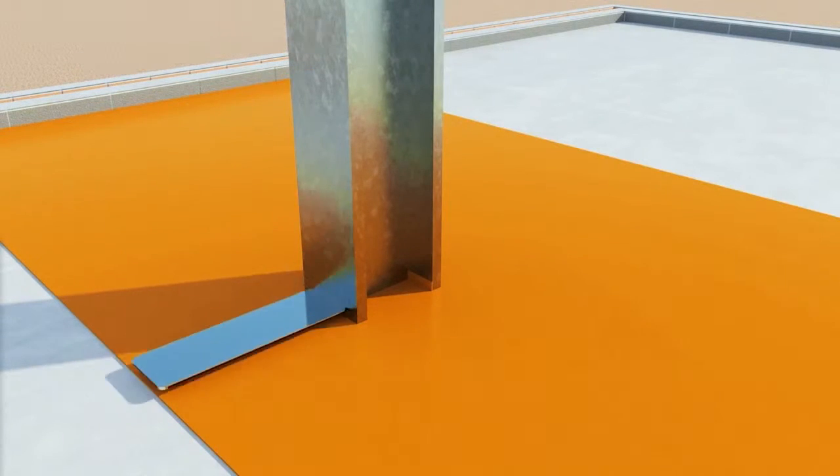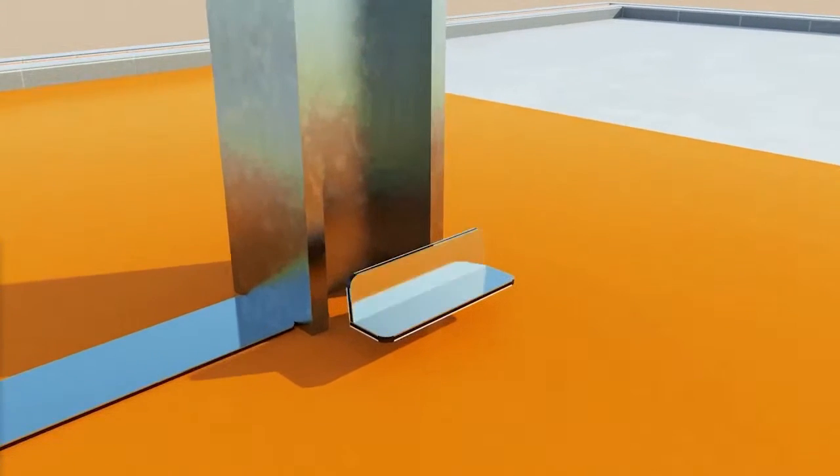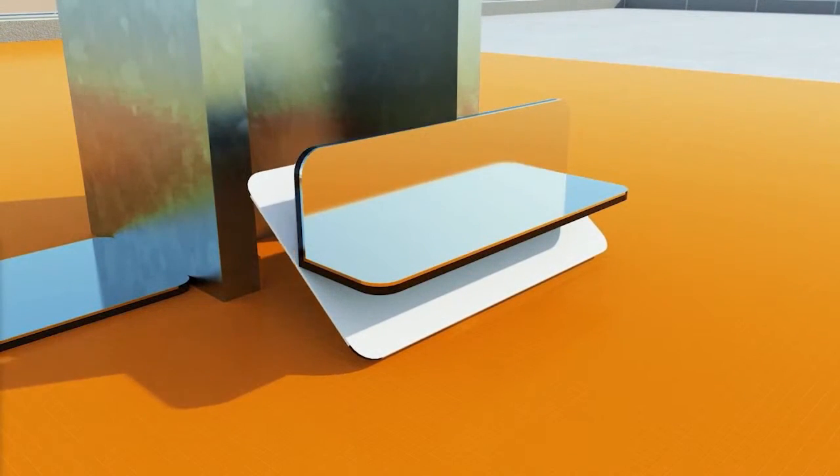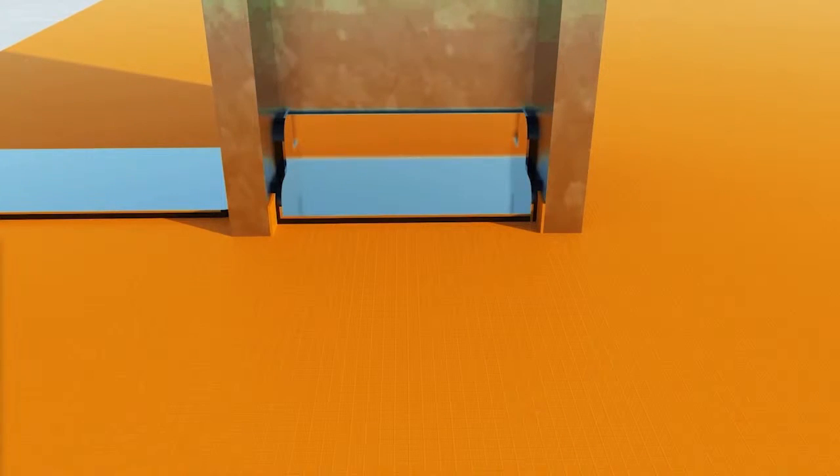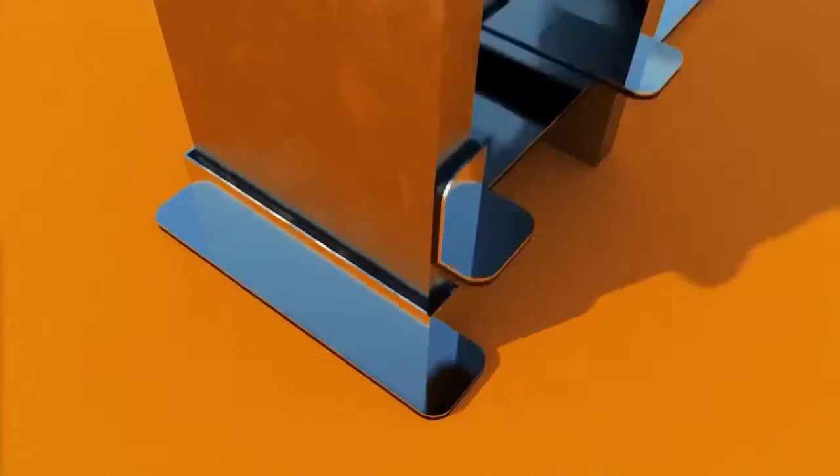Flashing tapes are usually less resistant to elongation than membranes, so it's important these areas are fully adhered to a properly supported substrate to limit the potential for movement. The rounded corners shown here are also important, as these are less likely to lift than a sharp corner and put less stress on the membrane and tape interface.